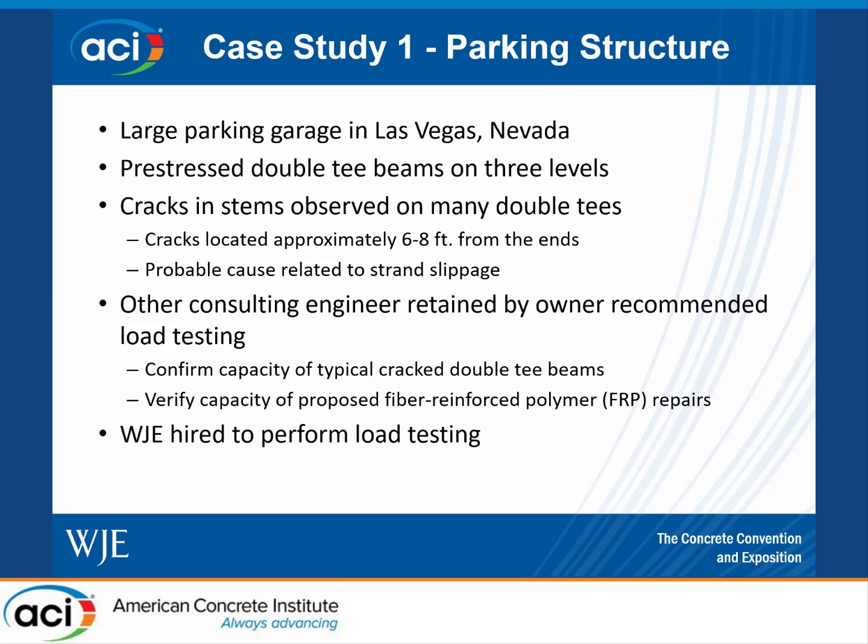All right, so I wanted to go into our case studies. The first case study was a parking garage in Las Vegas. There were pre-stressed double T-beams on 3 levels, and cracking was observed in the stems of the double Ts about 8 years after construction. The cracks were located approximately 6 to 8 foot from the ends of the double Ts, and the probable cause was related to strand slippage.